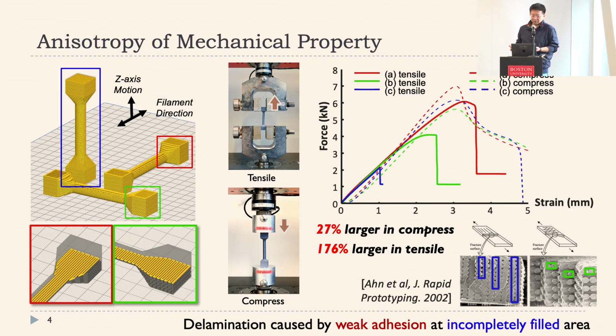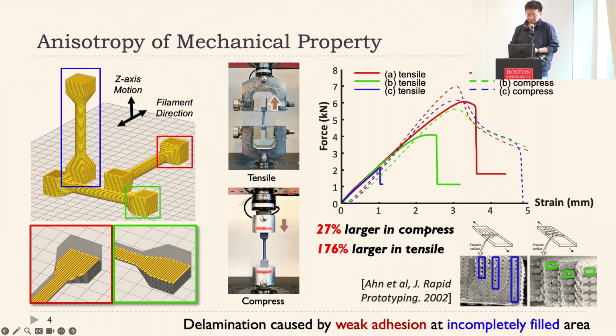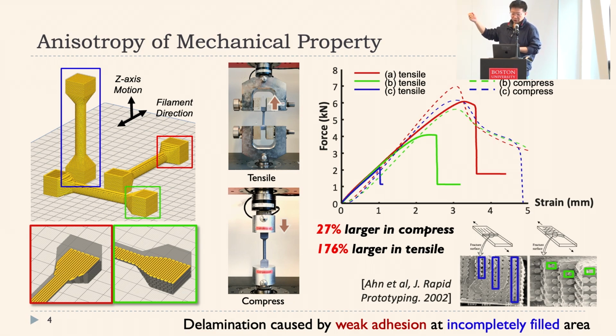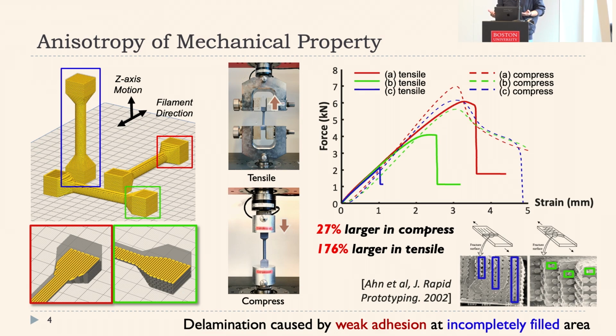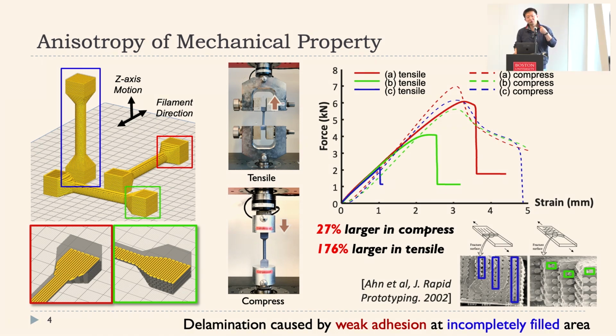One of the major reasons is that if you look at the microstructure of what you 3D print using filament alignment, you generally find many uncontrolled pores between those layers and between those filaments. That of course gives a very strong anisotropic mechanical property during your printing process. So we call it vector 3D printing because we are trying to align filaments along the direction they should be, and give you the strongest mechanical property in space instead of on the planar layer.